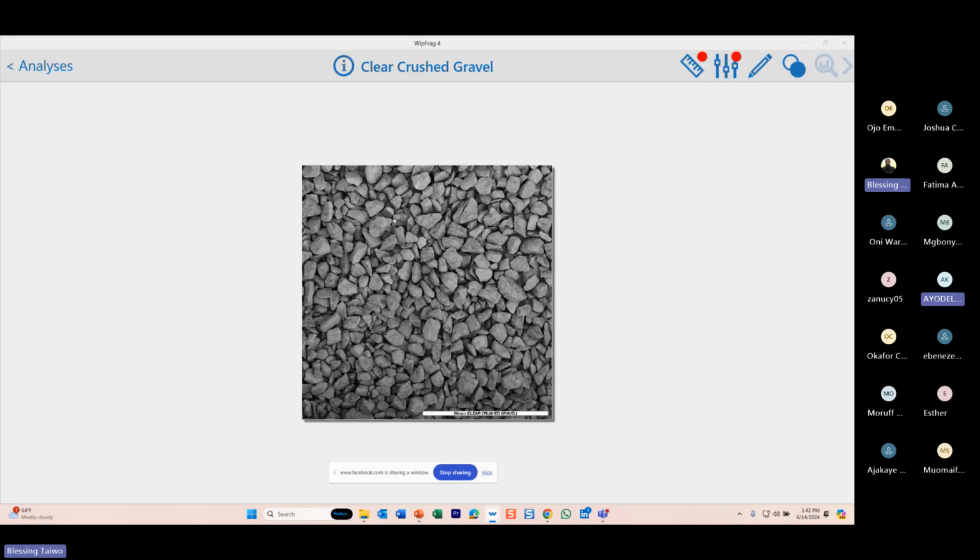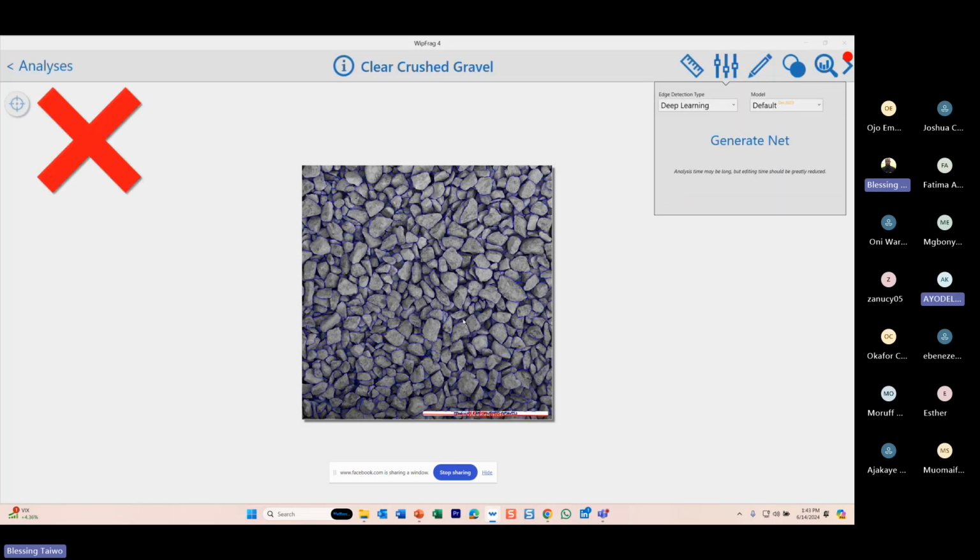So I'm using this as an example. The image you'll be using is blasted rock C. Set the scale. In this case, it's a single scale, and it is 65 mm. Put here 65, and it's mm, not millimeter, not meter, mm. Then we are done with the scale. Go here, generate the particle size curve. Assess the particle size as I've mentioned and ensure it is okay.